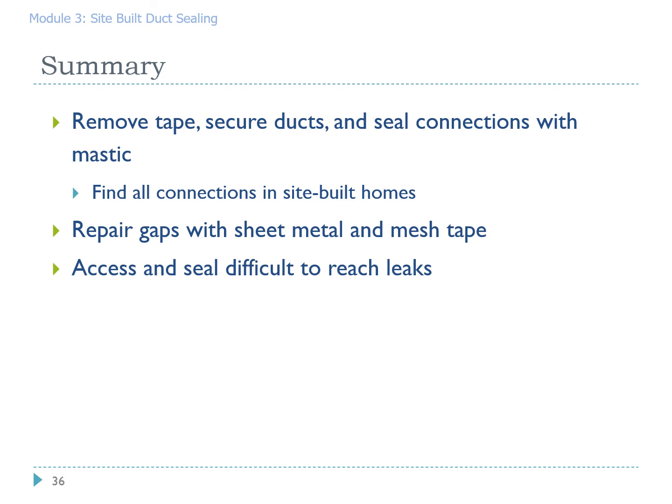Again, it's up to you to access and seal difficult to reach leaks. We showed you one technique, which is sometimes you get to cut one big hole to access smaller holes. Again, the basic tenet of the program is if you can reach it, you have to seal it, and in order to seal it, you have to mechanically fasten it. Thank you.